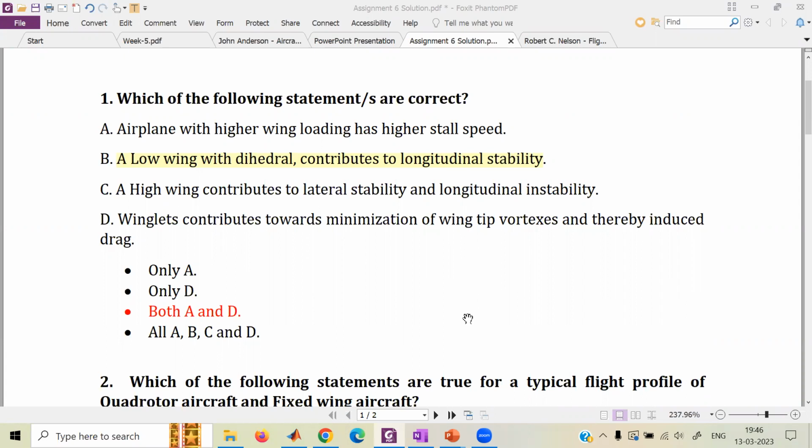What's the mechanism? Then maybe it connects to that point that there are components of velocity during a roll, and because of the dihedral angle, if the airplane is banking in, let's say, the right direction, then the lower wing will experience some upward force from down, and the upper going wing will experience a force in the down direction. Not down direction, I mean, there will be a lift, but that lift will be reduced on the wing that is going up. Yes, sir, that's my point.